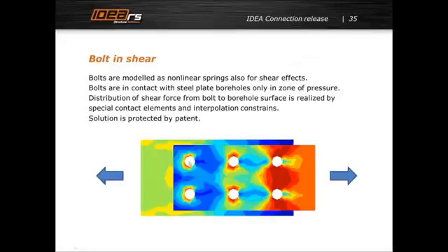And what we do here is that we have a special model which can transfer the shear force from the theoretical point of the bolt to the edge of the bore hole. We use again some contact elements here, and you see that the force is really put only on the part where the bolt is pressed into the material of the plate.